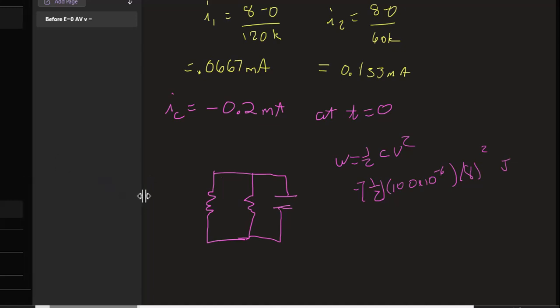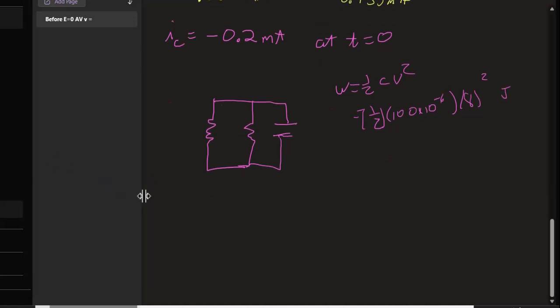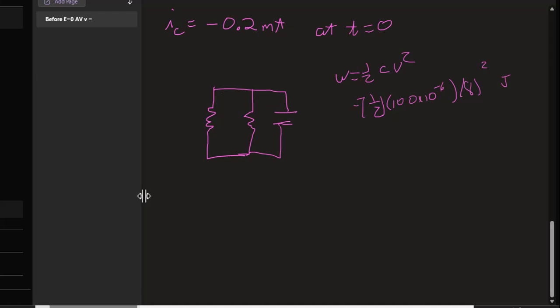So when we get to infinity, there's no more sources, so there's no source of energy, and so there's no more voltage, and there is no more current. So at t equals infinity, VC at infinity is 0, and IC at infinity is 0. So that's nice.